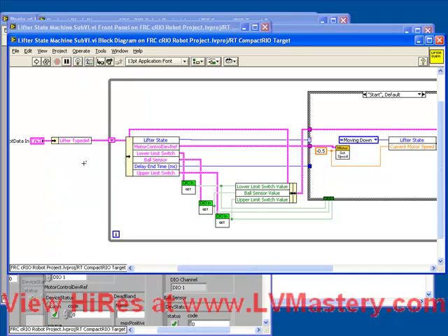What we're going to do is add a manual override mode, where a joystick button is going to turn off the state machine and put it into a manual mode where the joystick axis is going to move the motor speed of the mechanical lifter. This is going to make this example a lot more complicated, not only because we're adding states and modes to this state machine, but also because the Tele-Op.vi is where we're reading from the joystick. And that's where we need to write information that's going to come into the lifter. So let's look at how we're going to do that.